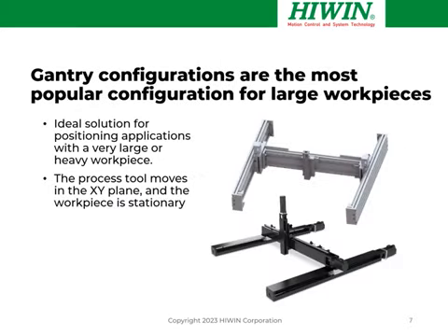When we need large workpieces or longer travels and a cantilever configuration isn't really feasible, the gantry is often a better alternative. A stationary workpiece in this case can be very large and very heavy because it's not moving. It also works very well with a conveyor to load parts, and very large travels are possible.